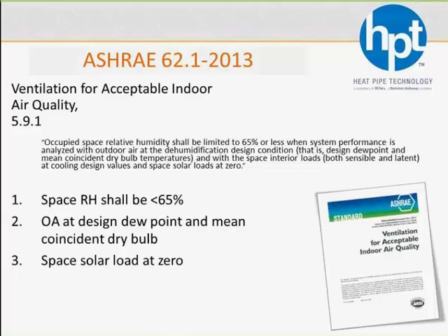The tricky days are when it's relatively cool outside and maybe it's raining and you're bringing in a bunch of that outside air. That thermostat may tell you that it feels great and you don't have to do anything. But the RH side, or if there's a humidistat, it's going to tell a different story and tell you that no, temperature-wise it feels great, but it's getting way too humid in here. We got to wring out some of this moisture.